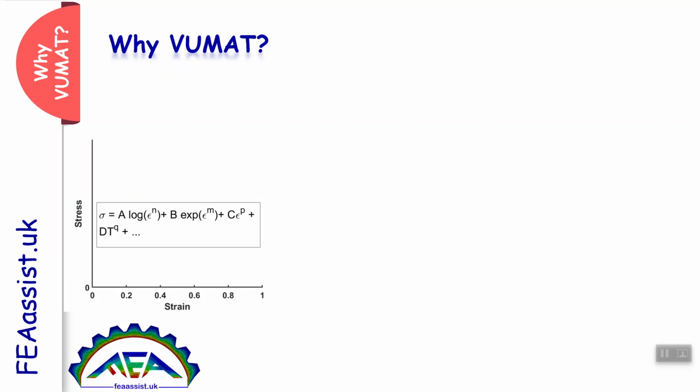But what if you have a new equation for a new material, a new constitutive equation, and the equation is not included in Abaqus to enter the parameters and constants? Then you will need a place to write your equations and force Abaqus to solve the problem based on your equations. This place is UMAT Subroutine.